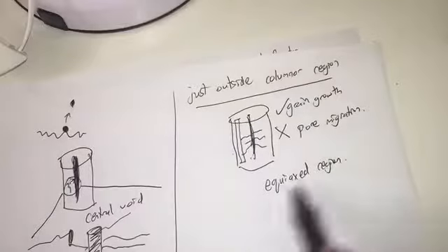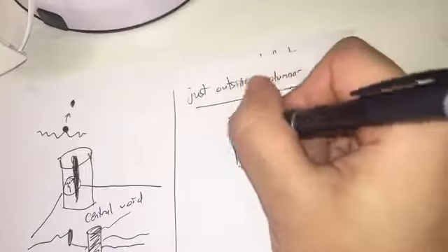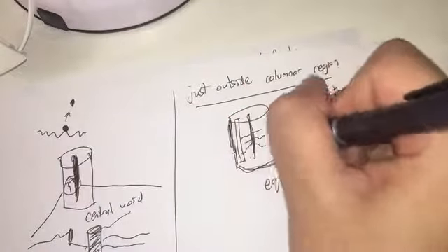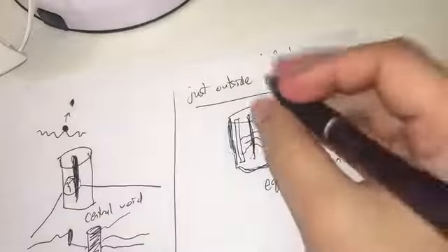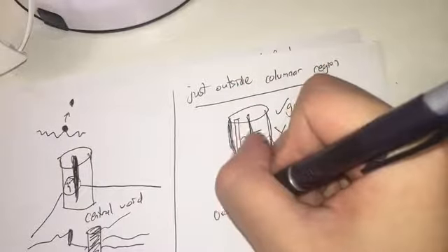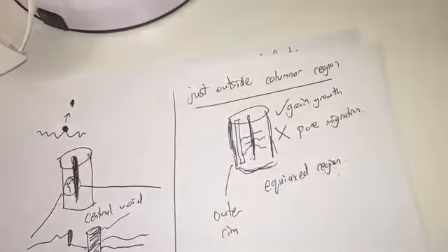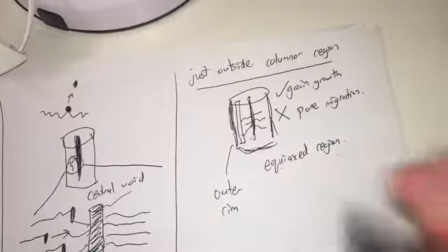Now outside the equiaxed region, that means on the surface, there is a minimal grain growth process, which constitutes the outer ring of the fuel pellet. Okay, so these are the major thermally driven processes inside the fuel pellet. Now, of course, as explained before,